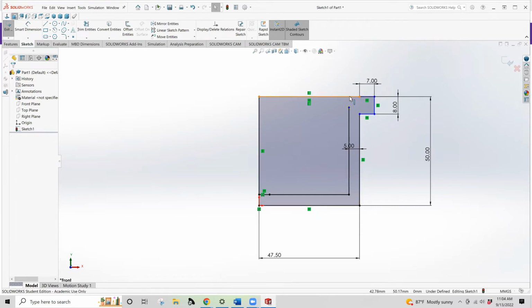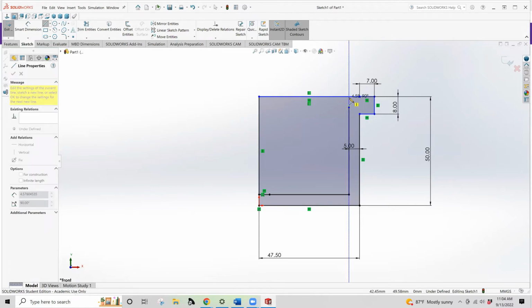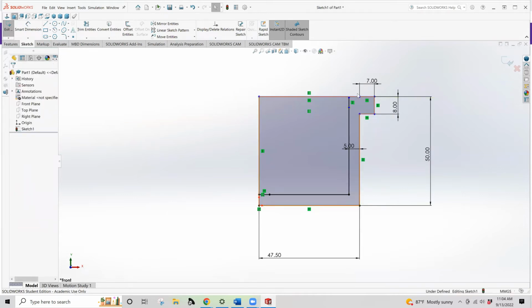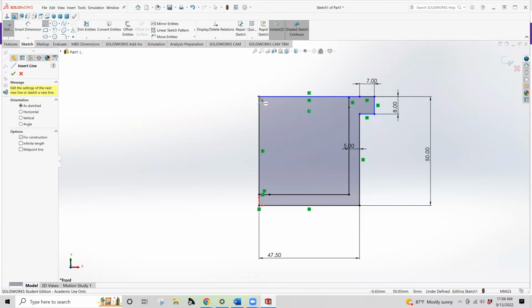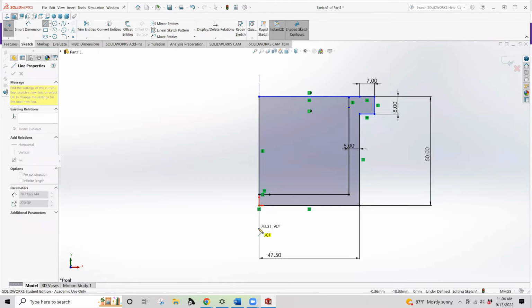So I will do close to that, but not quite here, to leave a sketch opening intentionally, even though it doesn't look like it. And we'll see what kind of errors that causes. This will bring up several things that we want to use as a reference. I'm going to add 2 center lines just for the sake of reference.